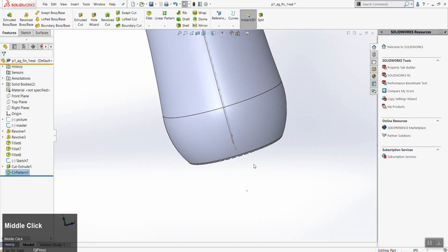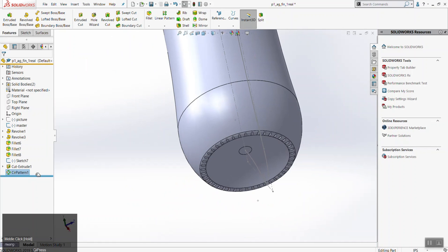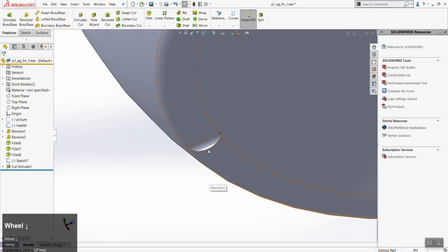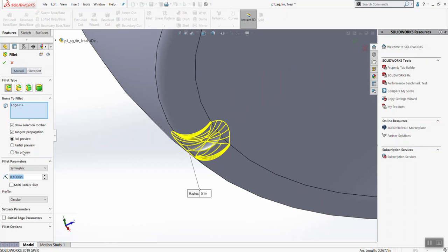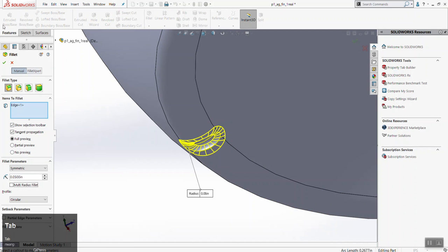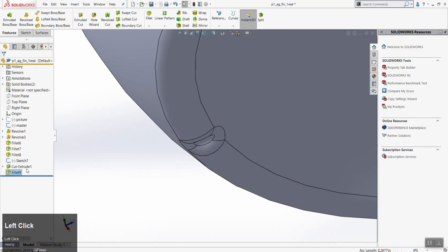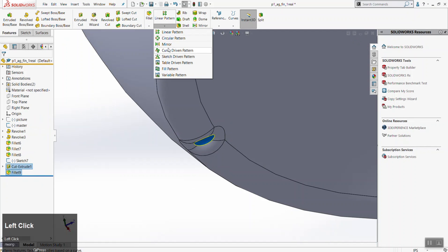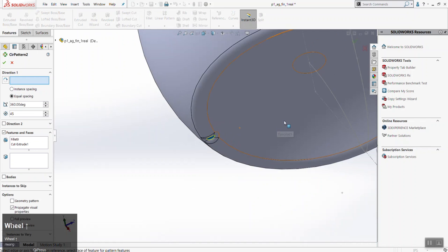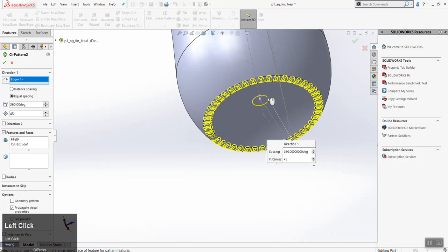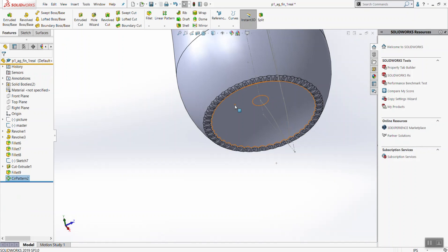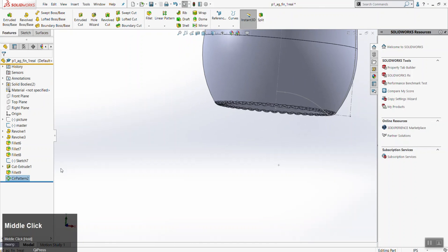Oh, can you just fillet one and then? Yep. Had I gone here and clicked fillet and filleted this edge, it's kind of big, so we'll go like 0.05. That's probably still too big, but that's all right. And now if I select both of these, I should be able to go to circular pattern. Because I think I did circular pattern first, and then I was trying from here to select what I want to pattern, and it didn't work. Okay. Oh, I see what you're saying. Let's try. Yeah, you can do that too, though.